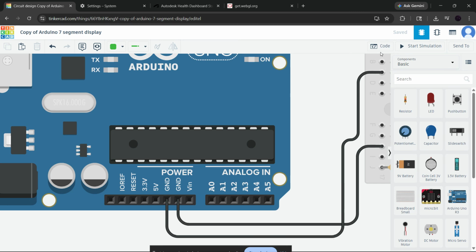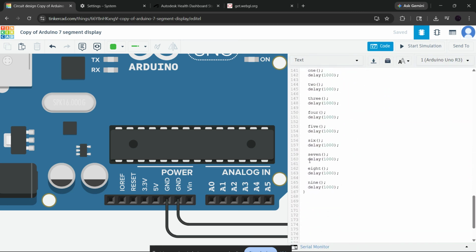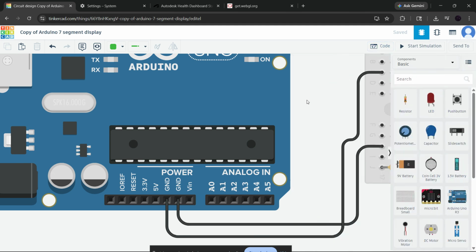So if Tinkercad says something went wrong, remember the fix is usually one of these. Refresh the browser, test Incognito mode, clear cache and cookies, turn on hardware acceleration, check WebGL, duplicate the project, simplify your groups, reduce imported file complexity, disable VPNs, flush DNS, check Autodesk status, and inspect your circuit if you are using simulation.